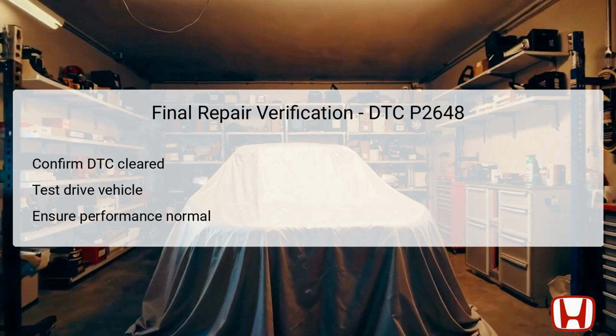Final repair verification is crucial after troubleshooting DTC P2648 to ensure that all issues have been resolved effectively. Start by confirming that the DTC is cleared using the HDS after completing necessary repairs. This step validates that there's no longer a fault in the rocker arm oil control solenoid circuit.